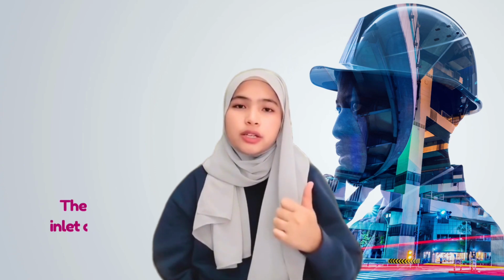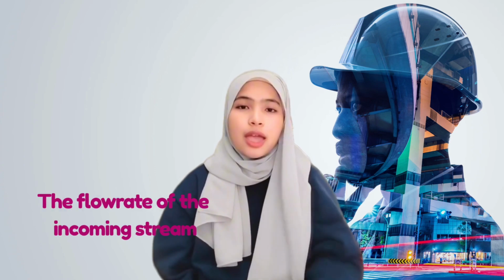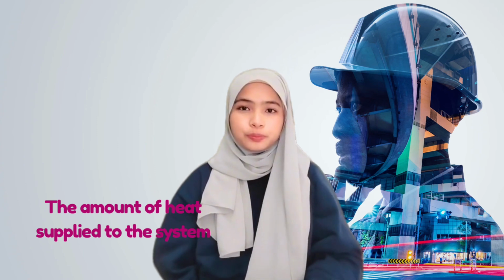The internal energy is expressed as density multiplied by volume and specific heat capacity times the temperature difference from a reference temperature. After substituting and simplifying, we get an equation showing that the rate of temperature change depends on 3 factors: first, the difference between the inlet and the tank temperature; second, the flow rate of the incoming stream; and the third one is the amount of heat supplied to the system.